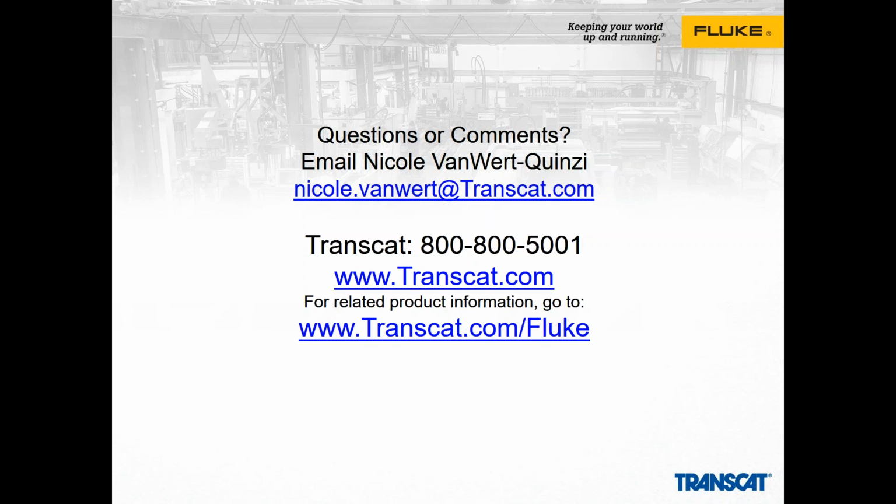Okay. Next question's a little long. I work with generator paralleling systems, and I have a customer that, during the time that we have generators paralleled with the utility and ramping load from and or to the utility, we trip a bus tiebreaker on a ground fault. This problem only exists while the utility and generator sources are connected together. It is believed that we have a positive sequence voltage imbalance, but still need to prove this assumption. We are using a Fluke 435-2. What would be the best method to measure this possibility?